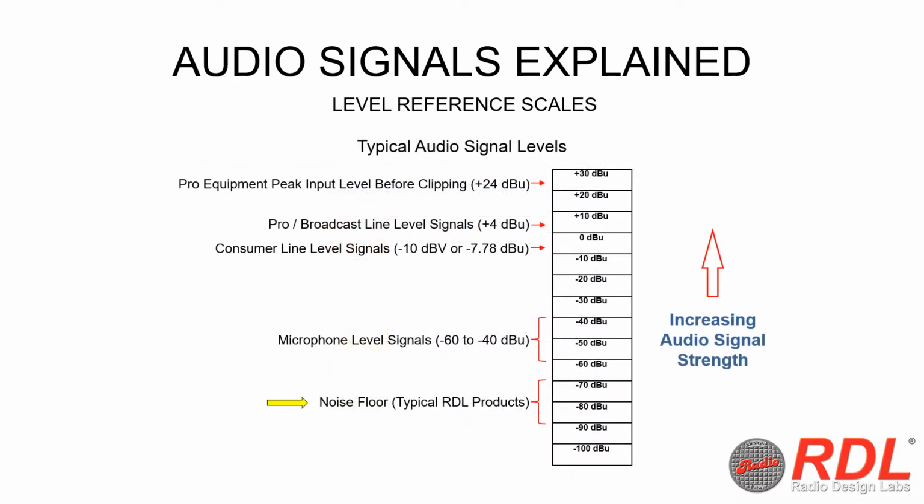This logarithmic decibel scale plays an important role in the audio electronics world. For example, when designing a sound system, you have to decide how loud a sound system needs to be for that particular venue. It's helpful to understand that doubling the total amplifier output, or watts, will only be perceived as a mild increase in volume level by the audience.